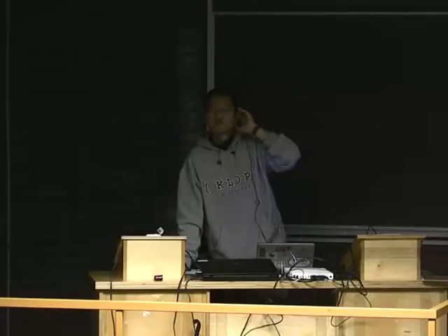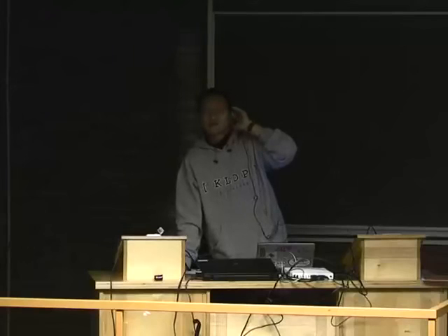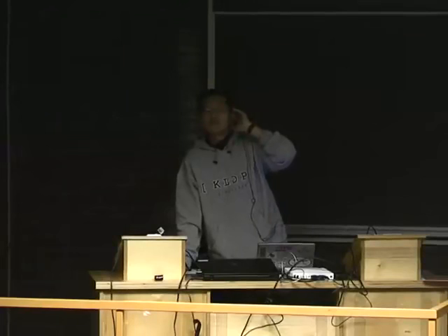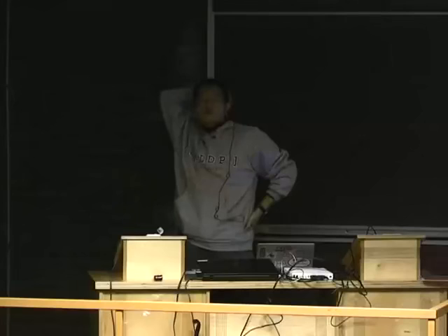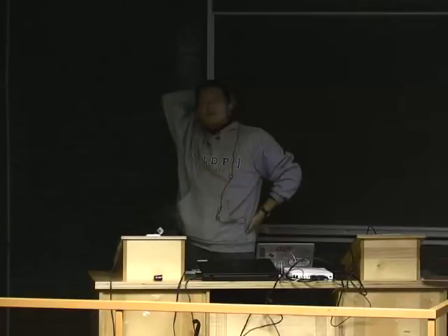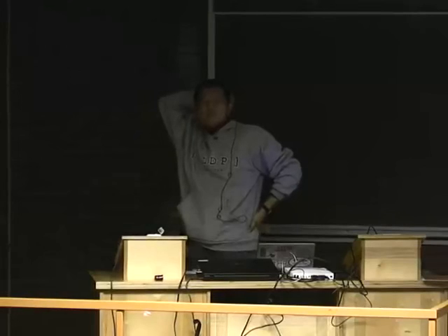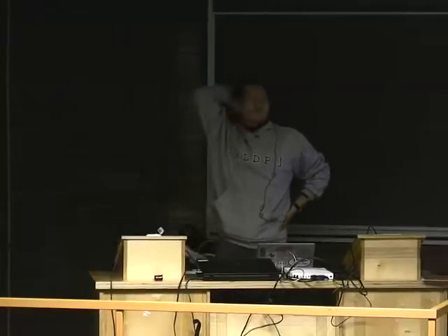Cool, that's nice to hear because I was experimenting with a similar topic, and this is the same solution I was able to create, to just read the last bit of the ADC. But I wasn't sure if it's enough, but if you say that you did some measurements and it's okay. Yes. And also some more expensive ARM boards have a hardware generator on board. Yes, STM32F2 has. If you are able to, or once the prices of these boards are lower, then you might consider using that as well. Yes, you're right. Thank you.